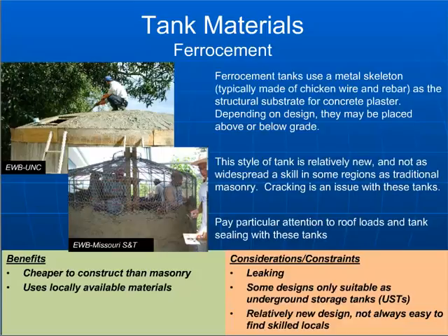They're essentially constructed with an iron rebar cage and then some chicken wire as a mesh, and then the cement part is just plastered on, so it's not actually like a poured concrete wall. And so the amount of materials that go into these tanks tends to be much less than your typical masonry tank or reinforced concrete tank.